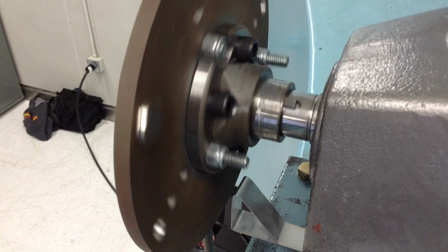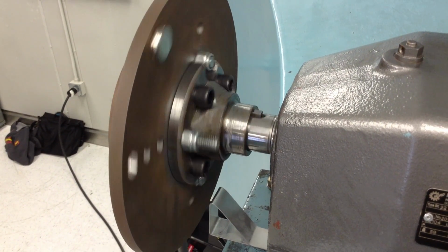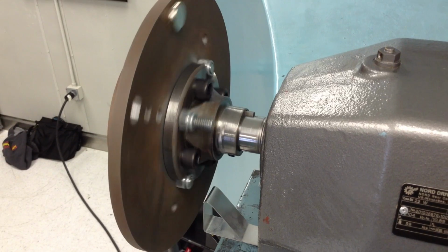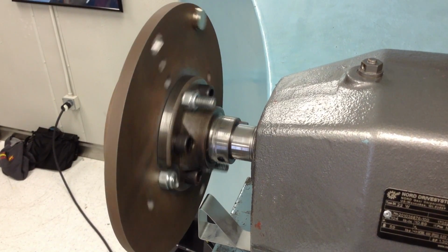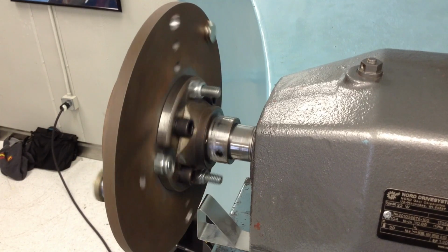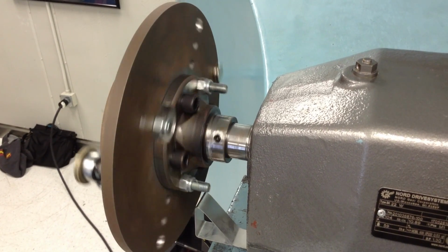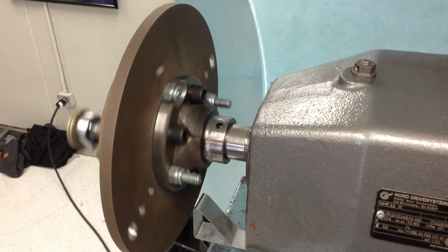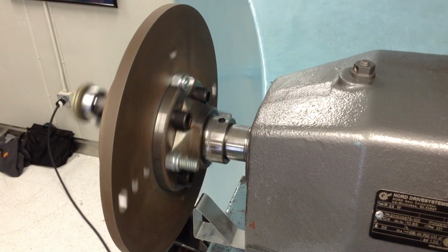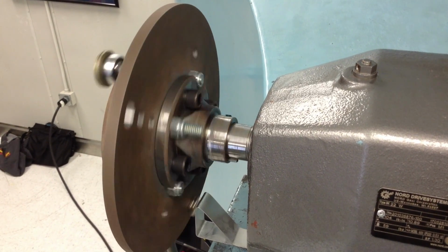Due to the nature of the dry plate material and the strength of the magnet used, our Hall effect sensor only required one magnet to turn it on and off. The steel used for the dry plate contains a large amount of iron. Because of this, the dry plate itself became magnetized. Therefore, as soon as the magnet retreated from the Hall effect sensor, the sensor encountered reverse polarity and unlatched back to a low signal. Essentially, the dry plate became our second magnet.